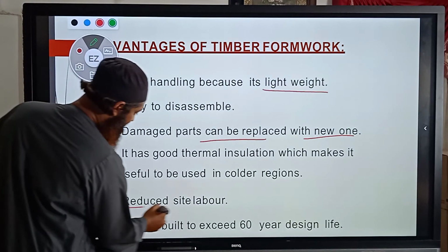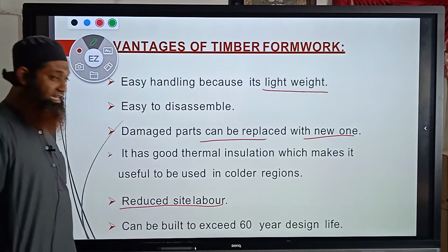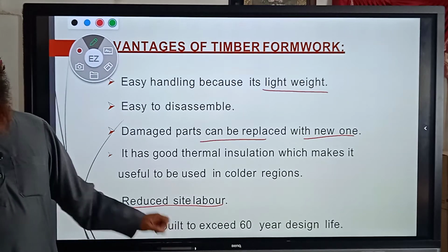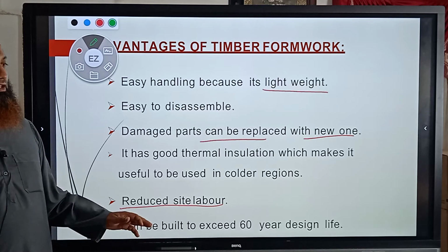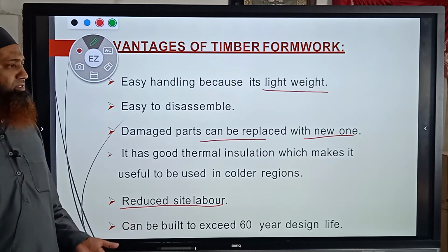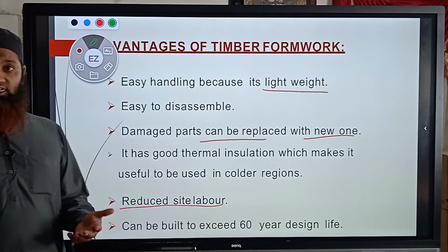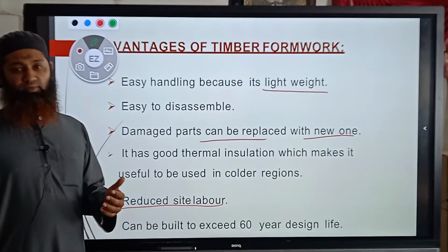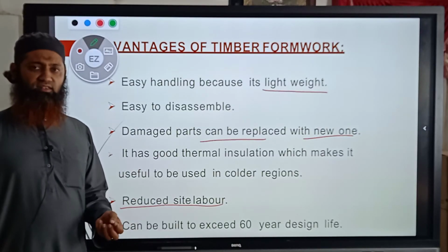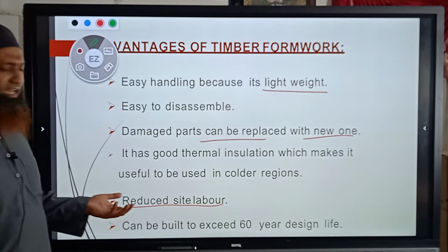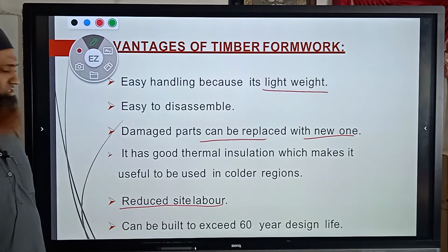Reduced site labor. See, because of this type of formwork, the labor is also reduced. Though if we use steel formwork, the labor has to be increased because of its weight and everything. Here timber is very lightweight, so reduced labor is also there.